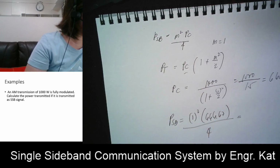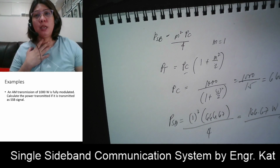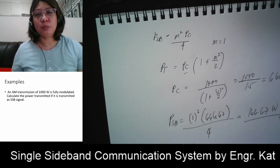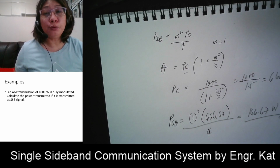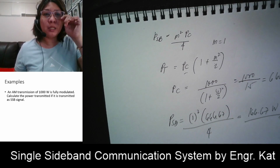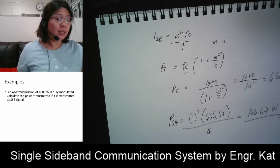So that is 166.67 watts. So that is the difference. For a conventional AM, you need to transmit 1,000 watts. But for a single sideband transmission, you only need to transmit 166.67 watts. Okay, so that is the difference.